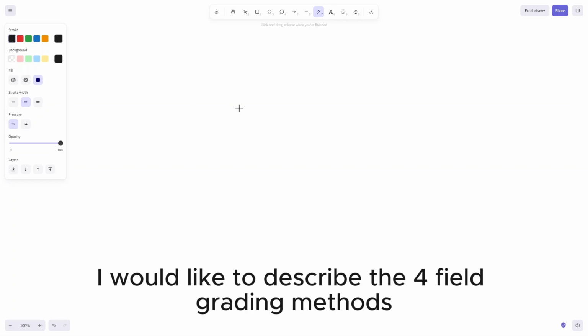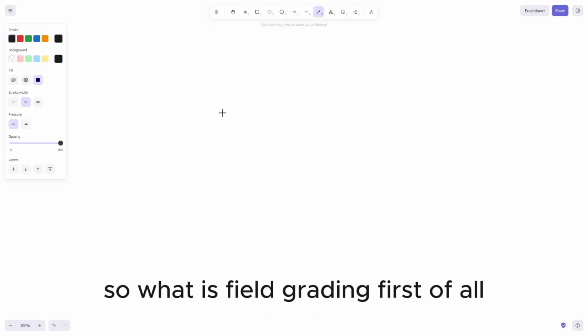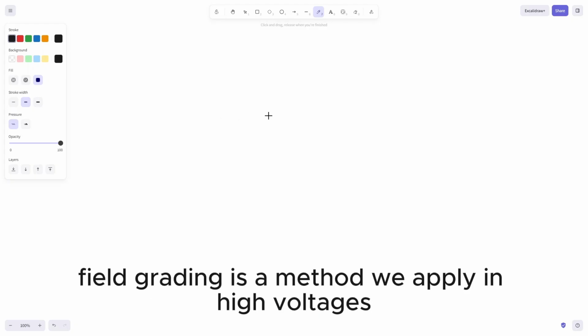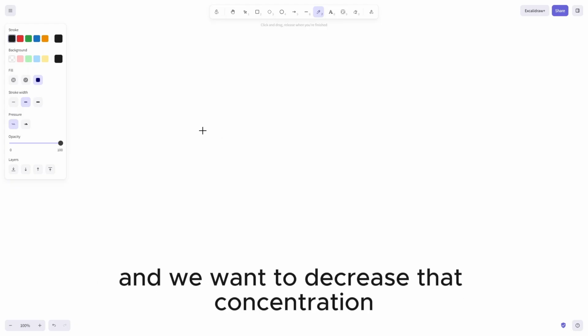In this video, I would like to describe the 4 field grading methods and explain the principle of cable termination. So what is field grading, first of all? Field grading is a method we apply in high voltage when we have a place where there is a too high concentration of electric field strength, and we want to decrease that concentration.